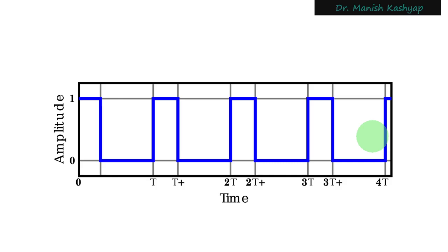And the specialty of the pulse that we need for operating this is it has a 33% duty cycle. So to be able to generate this pulse through a crystal oscillator, we have a specific IC for that, and we will see the structure of that IC when we study that clock completely in detail, right? So this kind of thing is needed there.